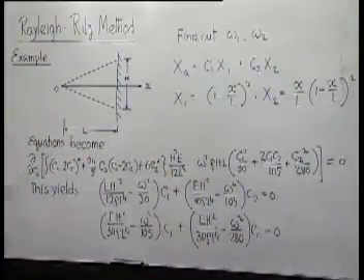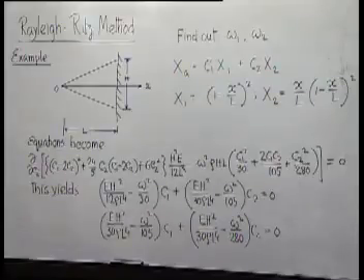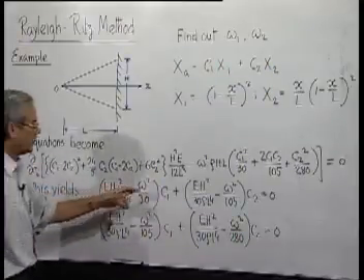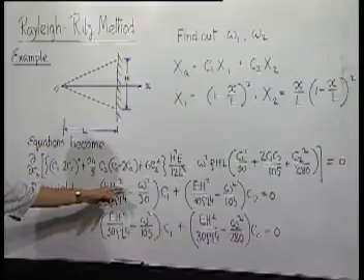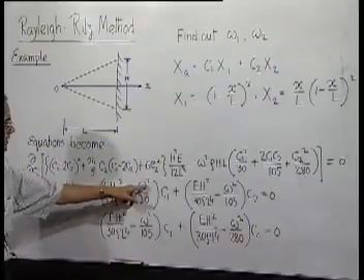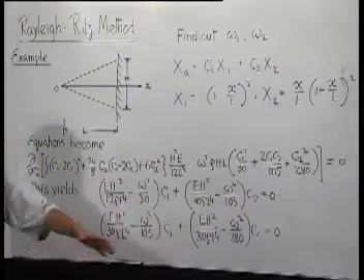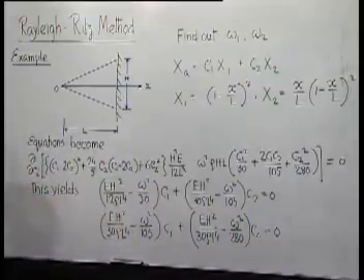So now these are our final equations, homogeneous equations in C1 and C2, and as I have been mentioning, a non-trivial solution will be possible only when the determinant of the coefficients equals 0, and we can see the determinant of these coefficients contains this term omega square. So this will ultimately give us an equation in omega square.